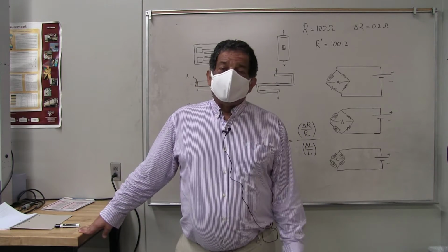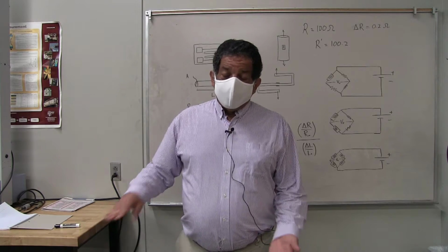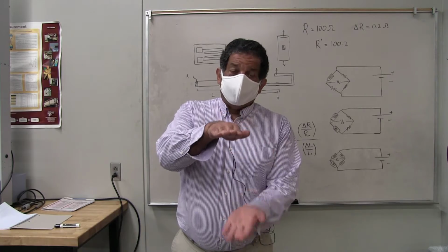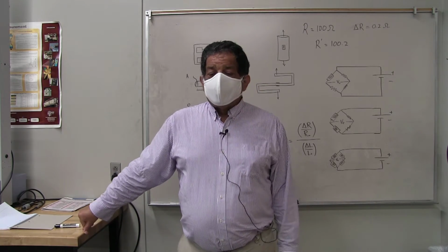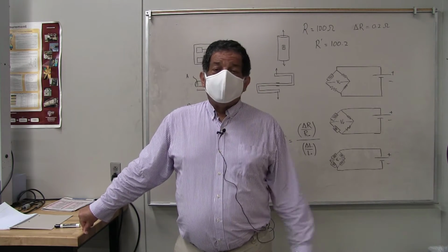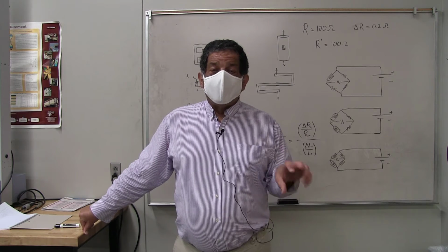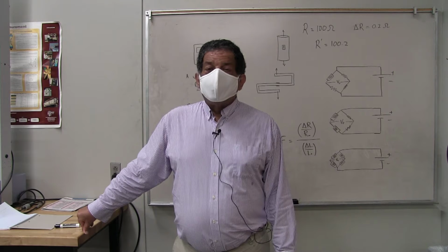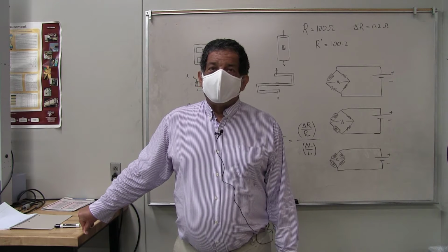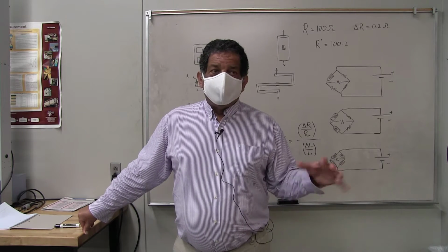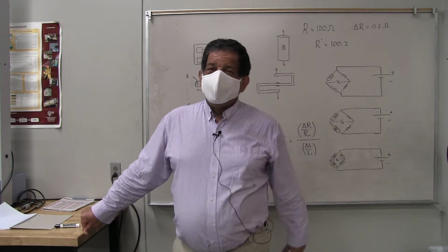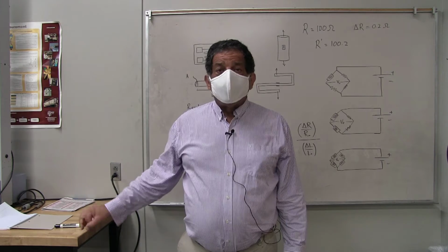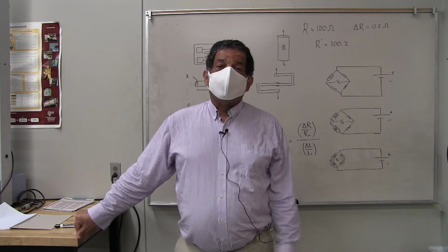The disadvantages of the air ride are that if you have a more compliant spring, that means when you go over a pothole, your wheels move more. And as a result of that change, there were some unanticipated problems. Namely, there were fatigue failures of their truck axles. And you don't want to be traveling down the freeway and a truck axle breaks and you have a dually traveling down the freeway at 70 miles an hour hitting cars. So we were doing an analysis of why it was that those truck axles were failing.